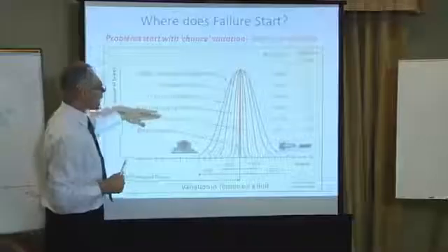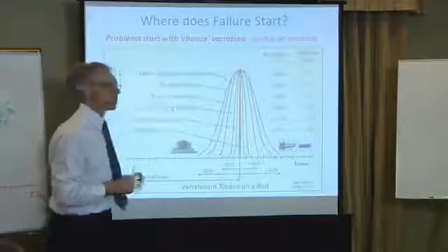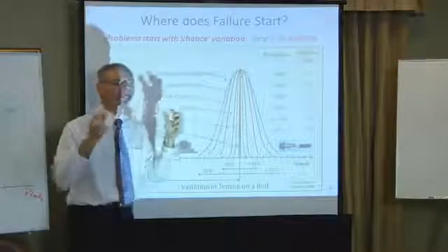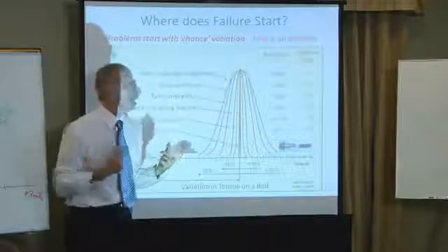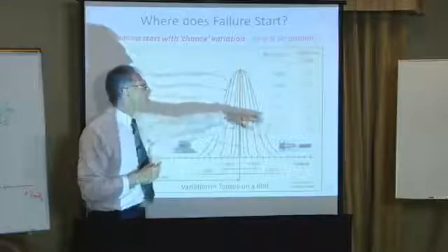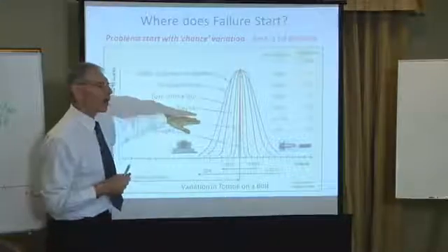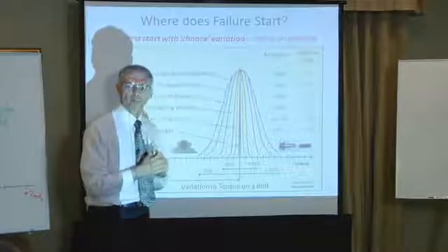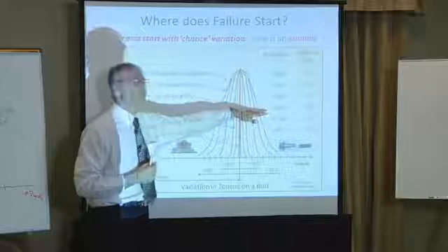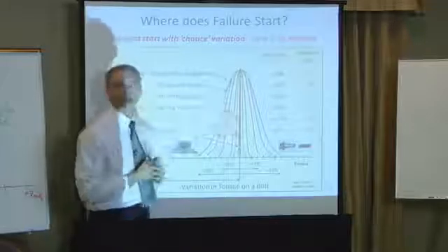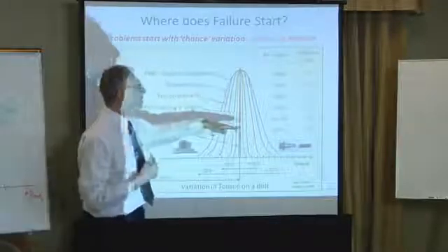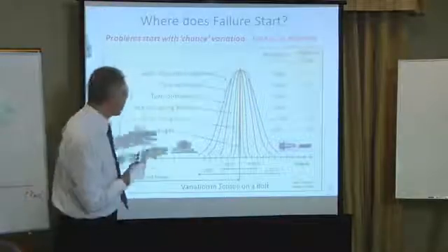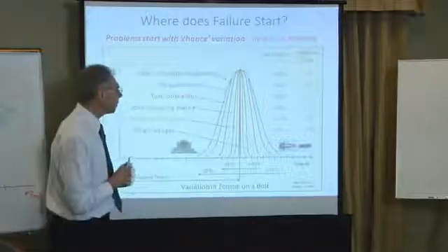Next one is load indicating washers. A load indicating washer is what it says. When the washer is squeezed to a certain point, a telltale evidence shows that it is now fully tensioned. And that is far more accurate. When I've seen these used in the mining industry in Australia, typically on vibrating screens with a lot of shaking of the fastener, the problem of tensioning goes away. So this says to me as an engineer, plus or minus 10% is about where you want to be in accuracy to prevent these sorts of problems.